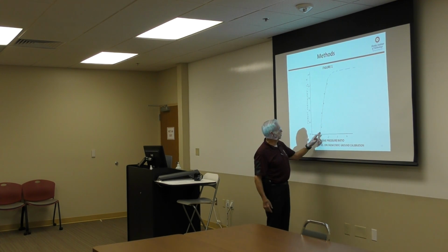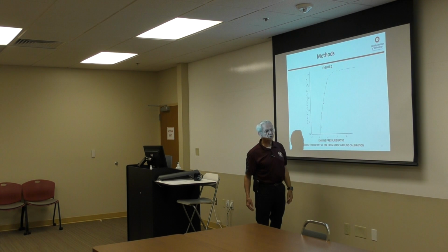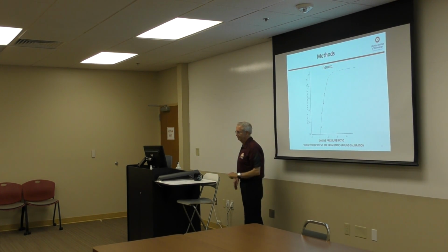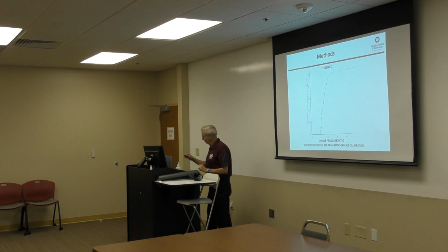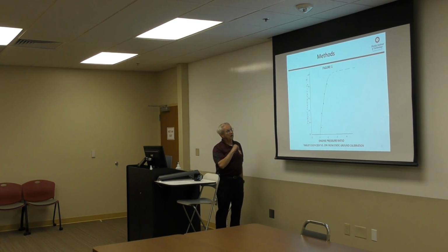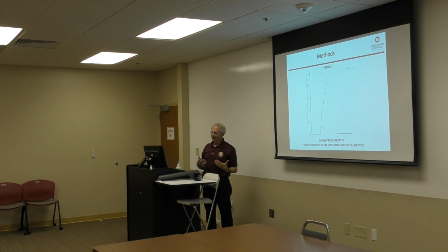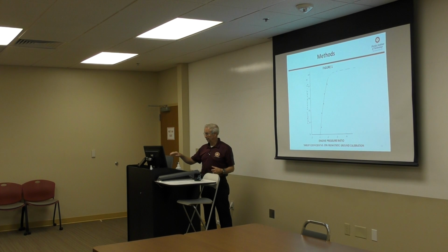And notice that it goes up, and then up there as it gets close to 100%, it kind of leans over, and of course the problem is finding where that break in the curve is. Because again, we're tied to the ground, right? We can't get as much thrust as we can in flight. In flight, we're operating at much higher pressure ratios.